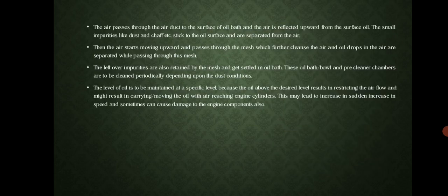The level of oil is to be maintained at a specific level because oil above the desired level results in restricting the airflow and might result in carrying or moving the oil with air reaching the engine cylinder. This may lead to a sudden increase in speed and sometimes can cause damage to the cylinder components also.